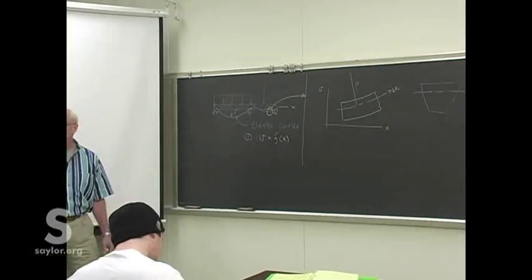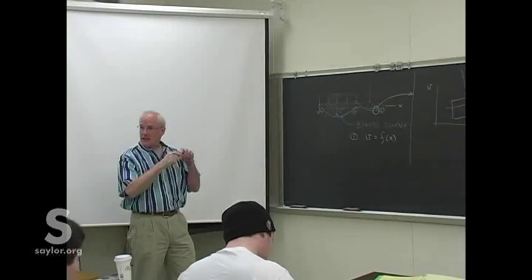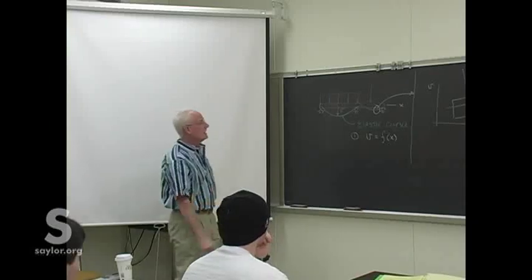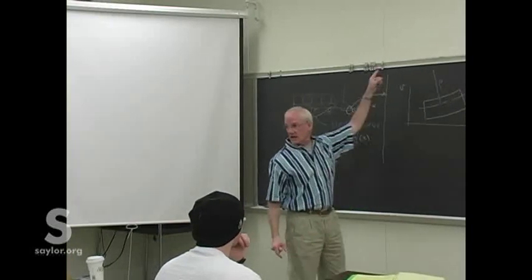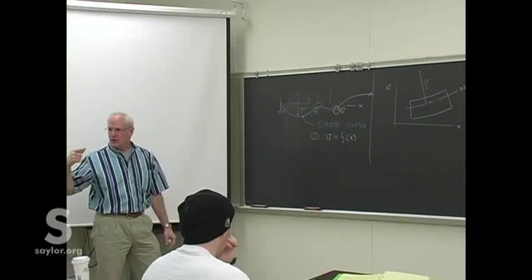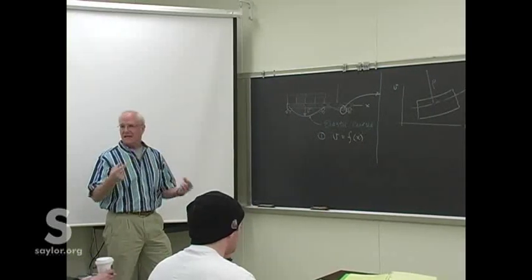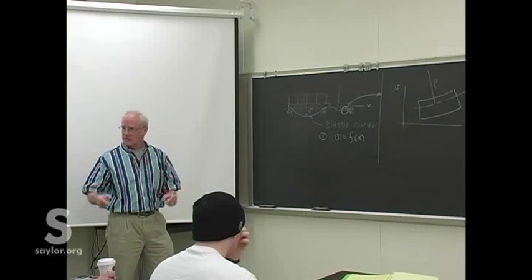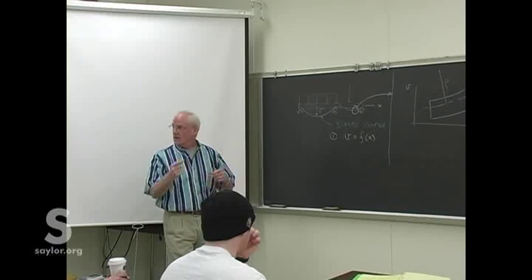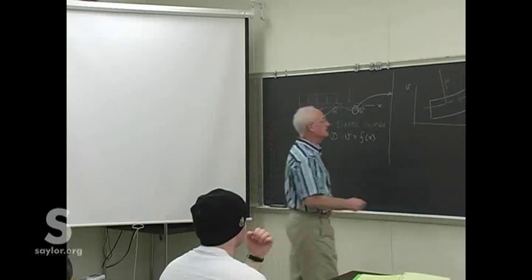In fact, there will be places where, because of the loading and the constraints, the beam actually has no curvature. It may have some slope, but it doesn't have any curvature. So the curvature is actually infinite at those places. And start bringing back in your calculus as you think of the functions you looked at. The second derivative especially told you what the curvature was and how to define where you went from one type of curvature to another. All those types of spots are going to be of some concern to us today.